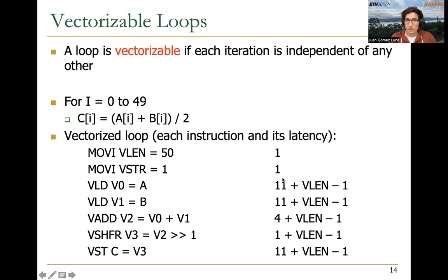However, because this is a vector processor, we can pipeline it, same as the memory access to the banked memory. What that means is that after having paid the latency of the first access to memory or the first addition, in this case, we will get one result every cycle.